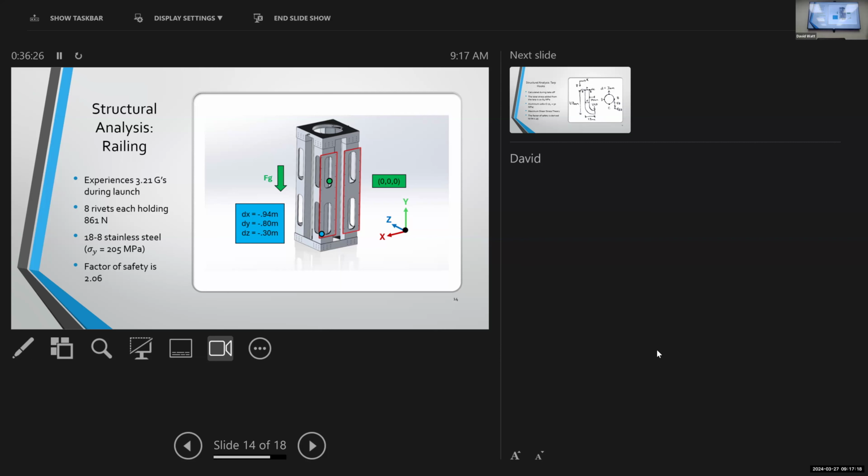So you're saying 1.5, and it's real common to hear factor of safety in aerospace is 1.5. That is somewhat of a simplification because there are different ways that structures can fail and different levels that we care about. So for a metallic structure, I would typically see a 1.5 factor of safety on ultimate failure, right?